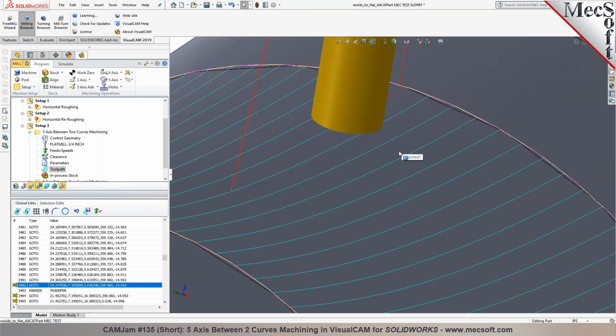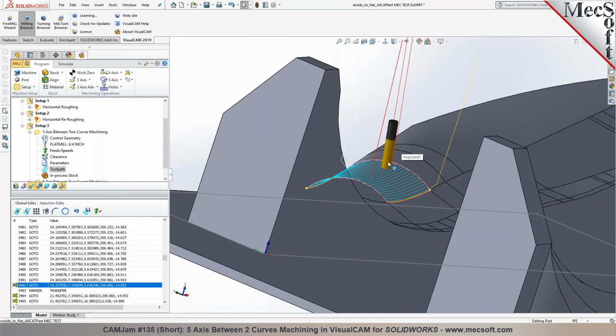So in other words, 0 degrees for C could be anywhere on the Z-axis relative to the machine world coordinate system. Yeah, C0. So how does it know where to unwind based on the world coordinate system? Well, what we do is all the toolpaths are computed based off your X, Y, Z0, C0, B0.